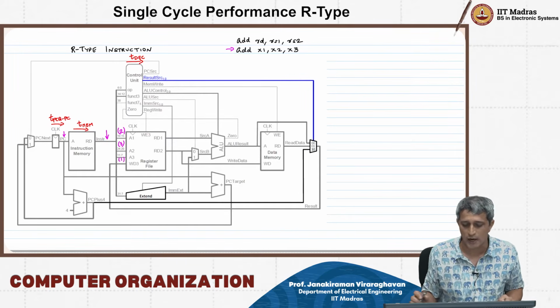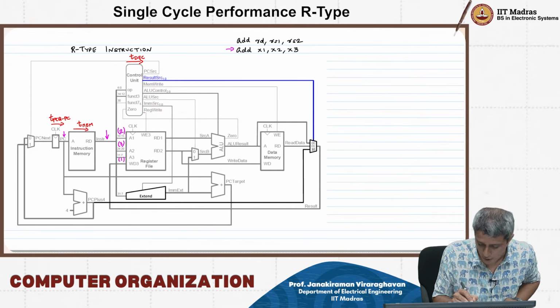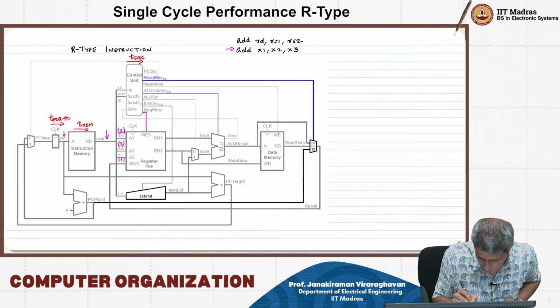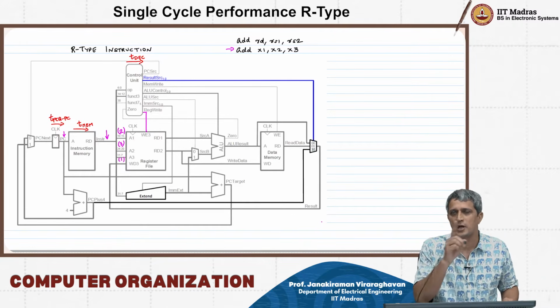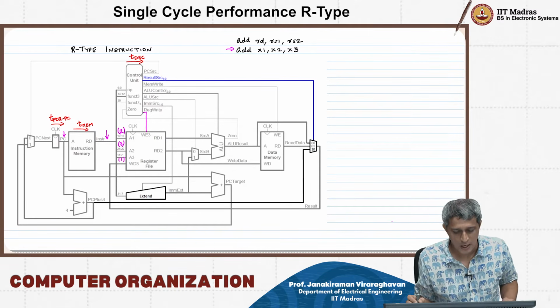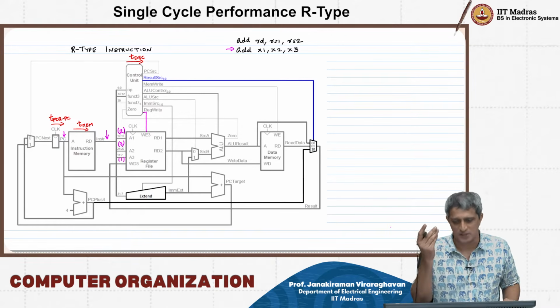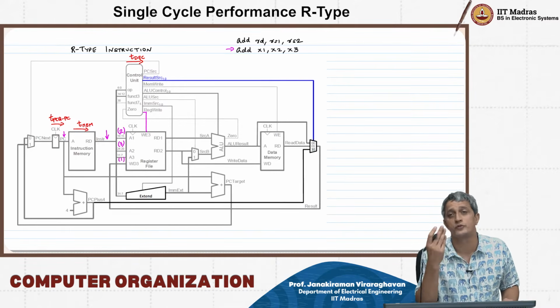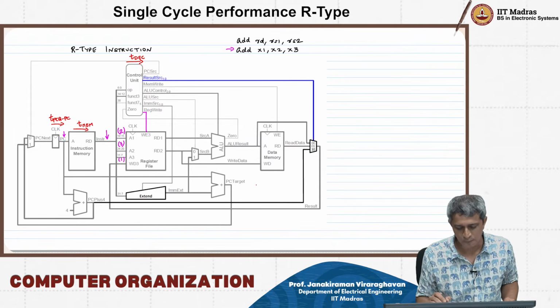So therefore if you look at it, for example, we would have enabled write enable here, right? Because we are ultimately writing back to a register, so this is going to be 1. Then your IMM source would basically be 0 because you are actually going to choose from the register, right? So therefore, that will be 0. I will not highlight it.